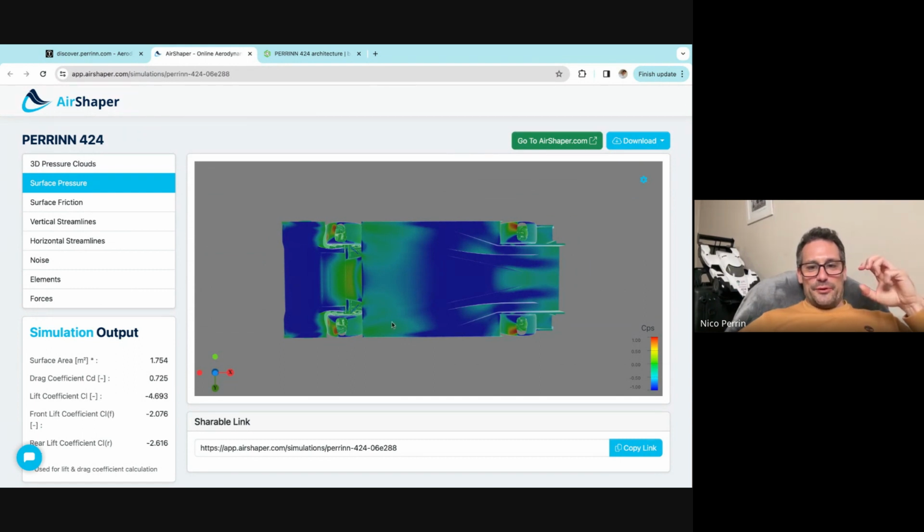So in front of it is a flat area of floor, and then the diffuser starts here. And if you can start the kick earlier, so more towards the front wheels, you will move that big area of suction to the front. This is a very nice way to rebalance your car. You cannot always do that. It depends how big the battery will be. So obviously there is a compromise with the size of the battery that dictates the floor to stay flat versus how early you can start your diffuser.